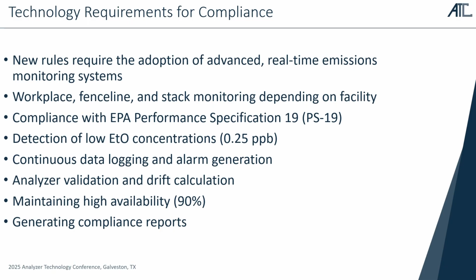Detection of low ETO concentration. So there are currently various gas analyzer vendors. They're present at this conference, and they're proposing different techniques of measuring low ETO. The two specific techniques that we've seen are cavity ring down and FTIR.